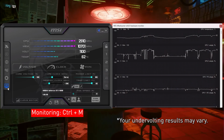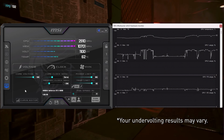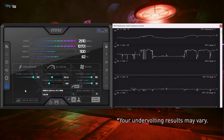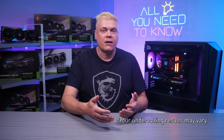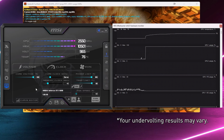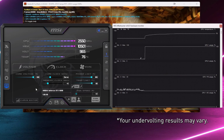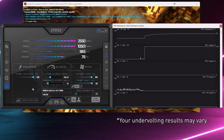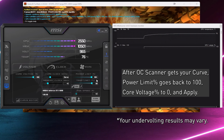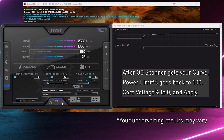You'll need to have Afterburner's graphs running to see the real-time GPU temp and voltage graphs. Run your favorite game's benchmark or play for a bit to know the frame rate to compare to later. Next, we'll run 3D Mark, Heaven, or FurMark for around 5 minutes and write down the frame rate average, voltage, and temperature readings, and we'll keep it running behind MSI Afterburner as we test to see the effect our changes have while the benchmark is running in real time. You can also use a utility like Hardware Info to cross-check live GPU temps and voltages.